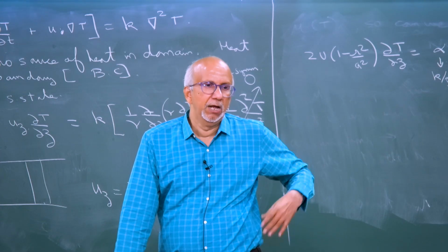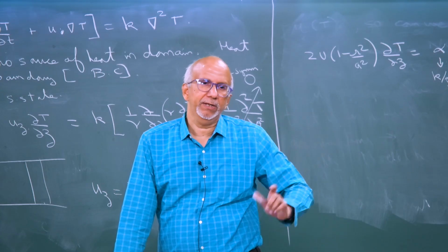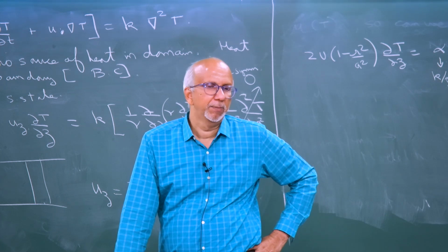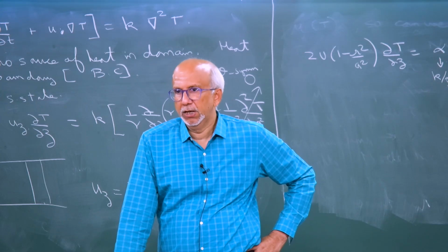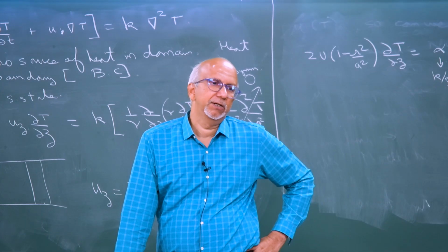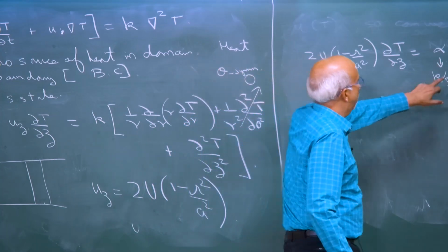So, when you are operating on a vector, you have to worry about the change of the unit vector with theta and all that. But here temperature and concentration are all scalars. So, there is no question of unit vectors, and that is the reason this Laplacian is going to be of this form.